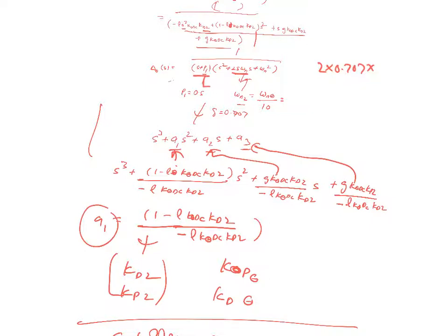Okay. So yeah, that's the $1 million question: how do I get the desired coefficients? You basically start with, okay, I want this system to be slower. So my omega n should be 10 times less than the previous loop, zeta 0.707. And for that pole we can play with it, saying, hey, let's put it at minus 0.5 or something. And okay.